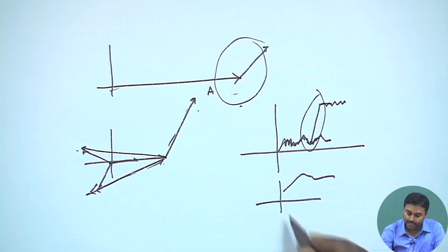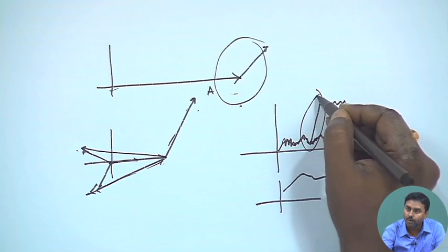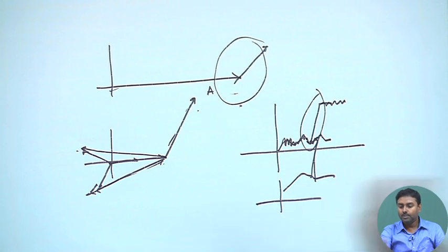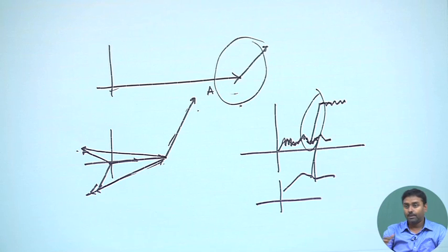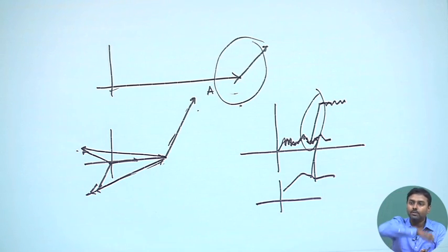So, all these slopes, if you differentiate it, what will happen? Suppose after differentiating I was getting this, but at this particular point, because there is a sudden jump, there will be an impulse noise created as many pi shifts are happening. Either positive or negative, whatever happens, there will be a positive impulse or negative impulse depending on the situation, and they will be coming randomly, because with noise characteristics you do not know when it will do that pi shift.